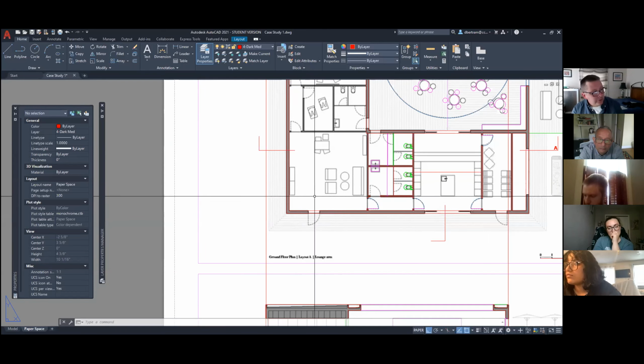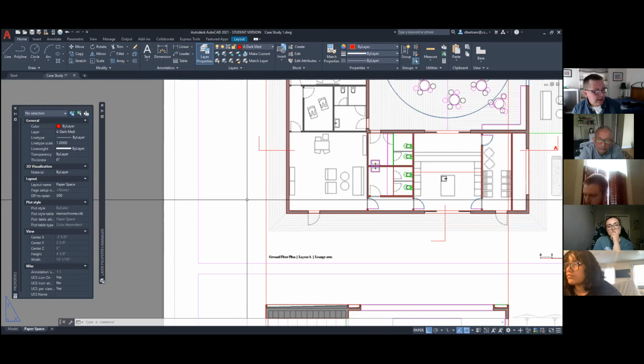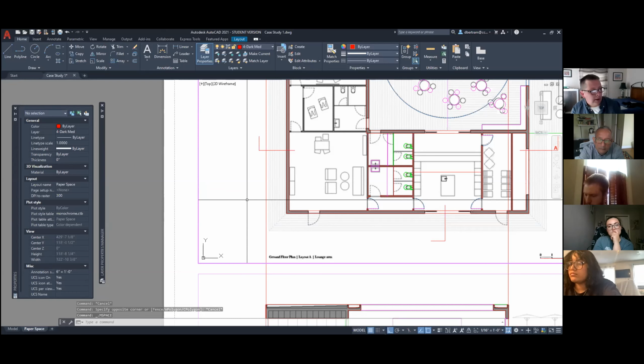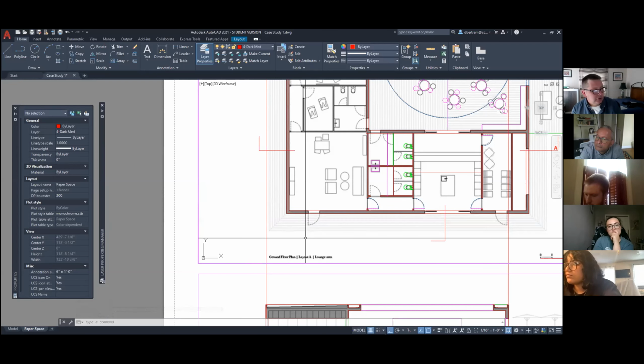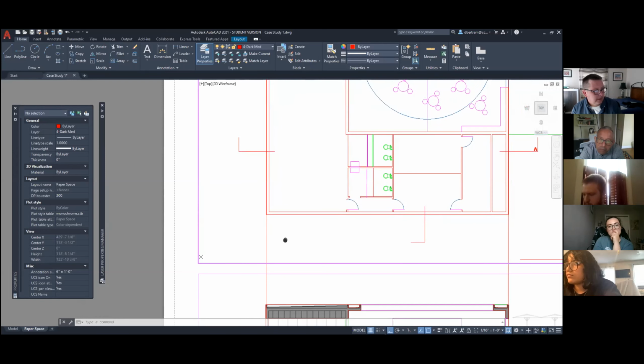What I have to do is move this building so this wall aligns with my section. So I'm going to double click to get inside again, but now I am not going to scroll. If I scroll at all, it will mess up my scale. So I'm just going to push down and drag it over.